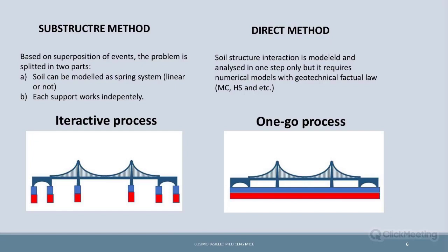In this case, each support works independently. Each support works mainly with a horizontal subgrade modulus and a vertical subgrade modulus to simulate the base resistance if the foundation has a pile resistance.